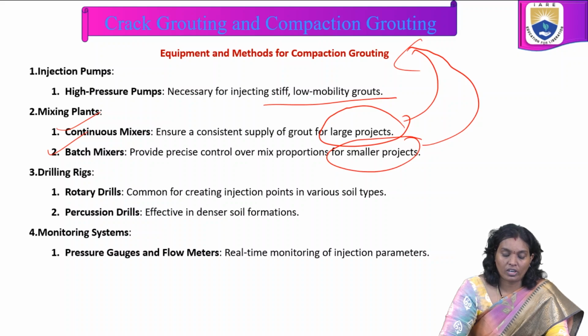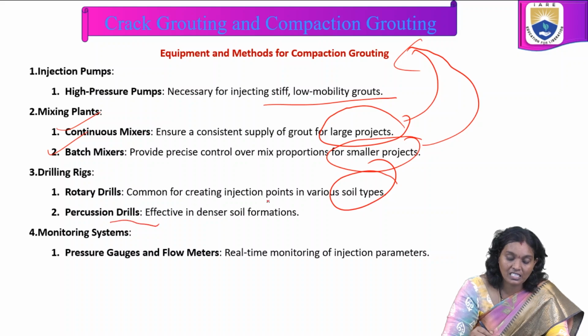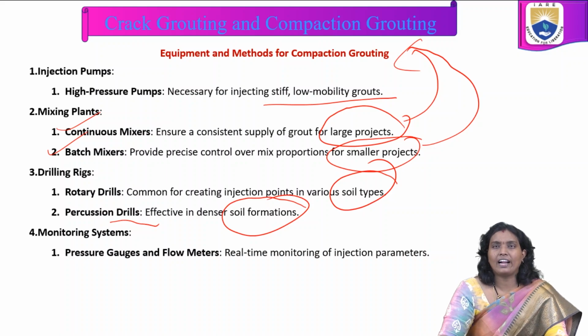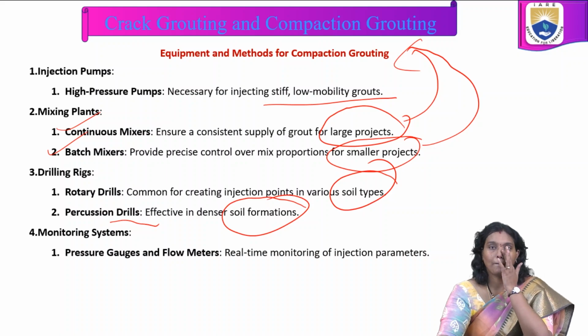Drilling rigs: rotary drills, percussion drills. This is common for creating injection points in various soil types, and these types of drills are effective in denser soil formations. Monitoring systems: real-time monitoring of injection parameters is important, and this depends on pressure gauges and flow meters.